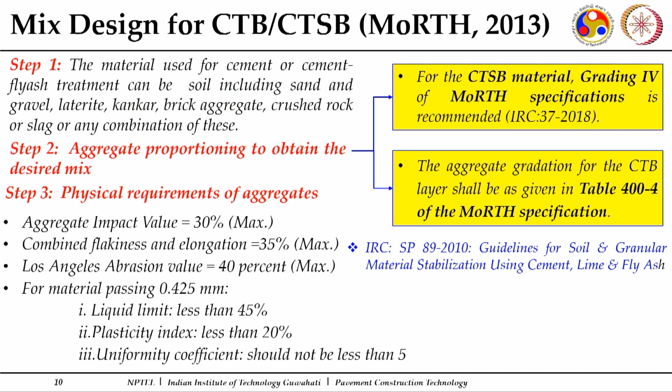In addition to this, nowadays in certain regions many materials may not be good enough or suitable enough to meet the strength requirements in terms of CBR, or the individual aggregate requirements, and we require a good quantity of materials for the construction of these unbound granular courses.